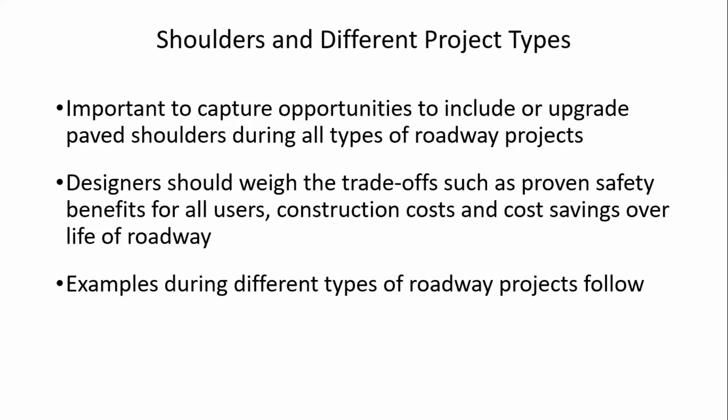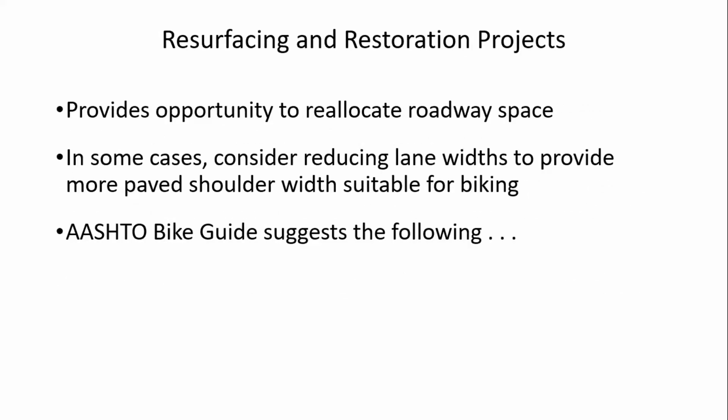And I'm going to share some examples of shoulders and shoulder widths during different types of roadway projects. We'll look first at resurfacing and restoration projects. This gives us an opportunity to reallocate roadway space, and in some cases, think about reducing the lane width to maybe provide more paved shoulder width that would be suitable for bicycling.